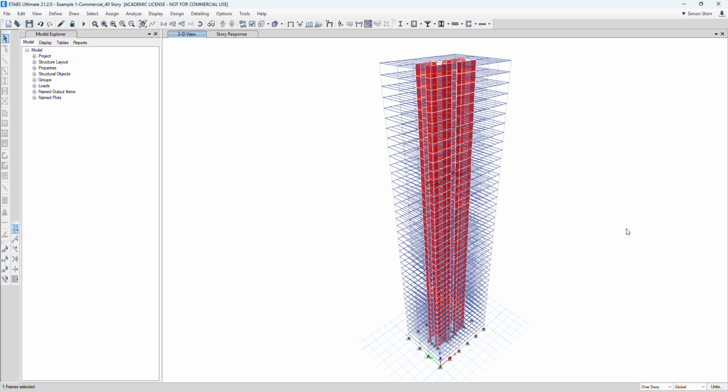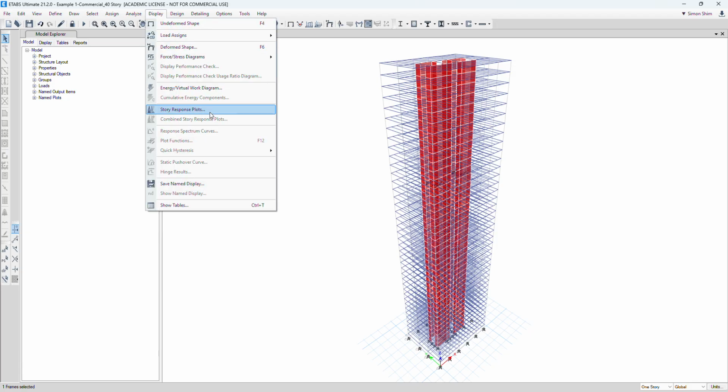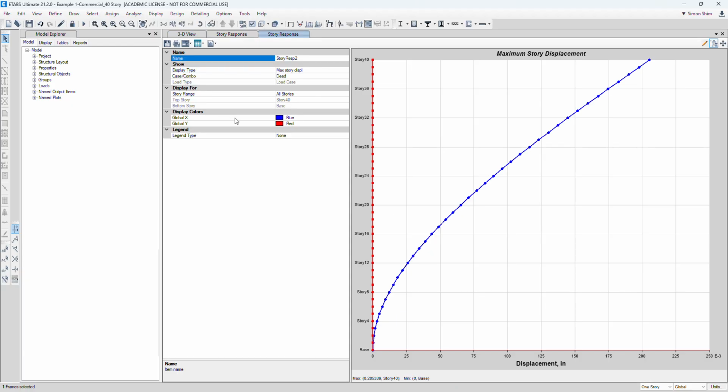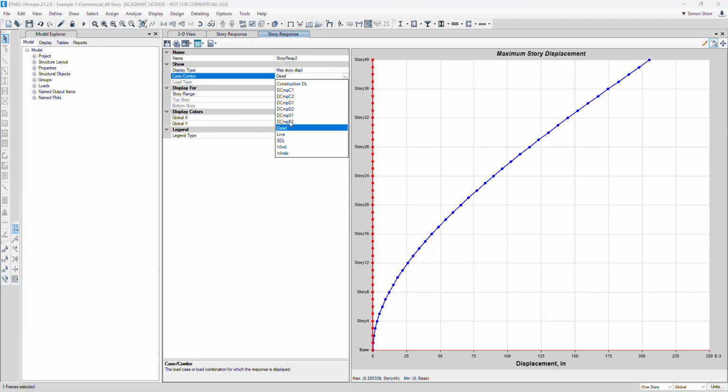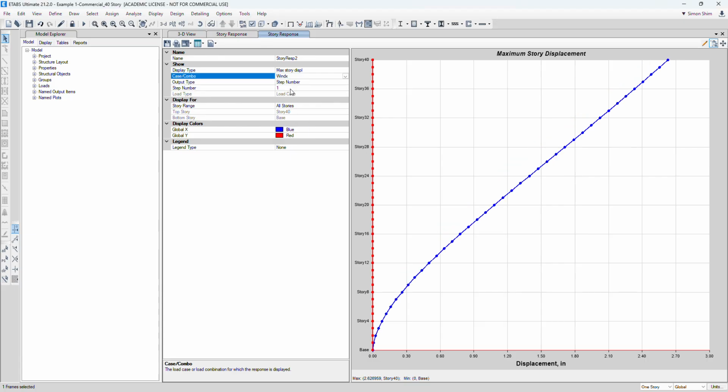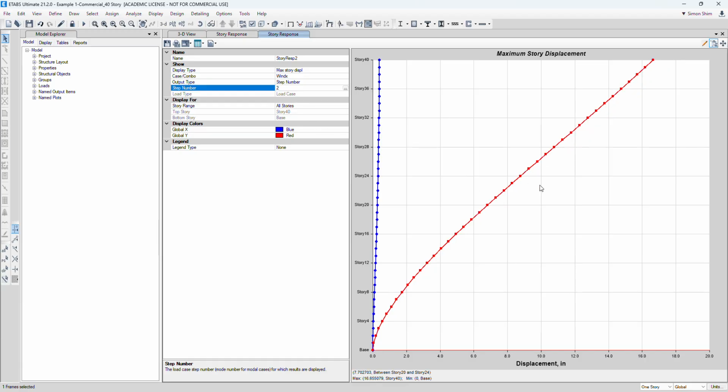All right, just checking the serviceability check. So I'm gonna plot out the deflection diagram, again displays and flow chart. I'm gonna choose the service wind. And then instead of looking at the wind blowing X, because that's a strong axis, we don't have any significant deflection. It's pretty small. But by changing to wind blowing in Y direction, this example shows me 16.65 deflection